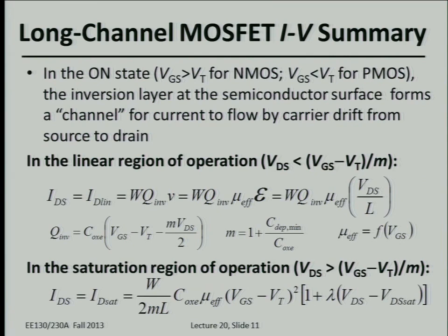Yeah, so you want to shrink the thickness of the gate oxide so you can have higher capacitive coupling between the gate and the channel. In other words, you have more voltage applied across to the channel. And in any case, you have more inversion layer charge density, right? If you increase Cox equivalent by thinning down the gate oxide. Okay, what else? Better material, like maybe higher mobility. Okay, so in recent generations of technology, people have come up with novel ways to enhance the effective mobility of electrons or holes traveling from the source to the drain. So we'll talk about that probably next week.